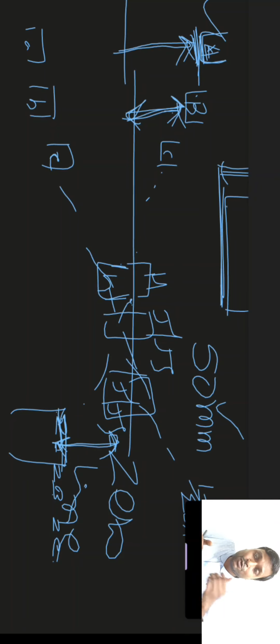So when the hole is above the zero line, fundamental deviation will be the lower deviation or écart inférieur, and when the hole is unilateral, that is on one side of the zero line, but it is below the zero line, then in that case the fundamental deviation will be the upper deviation or écart supérieur. Now come to the fundamental deviation of the shaft.